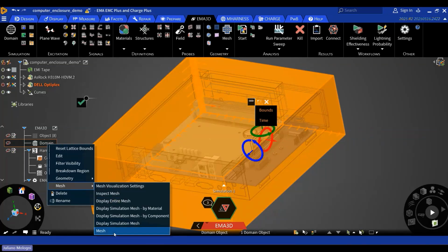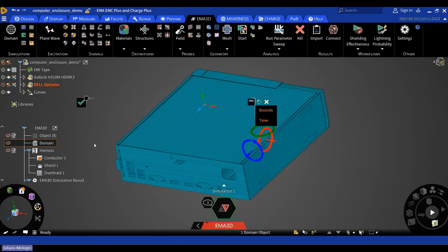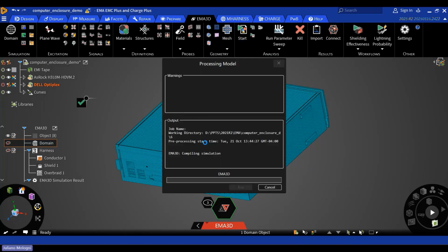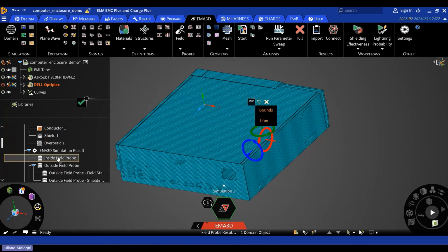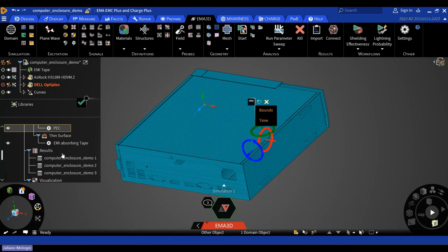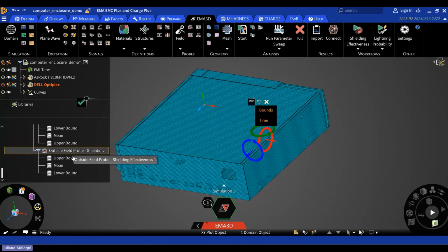You can get noise that is being induced in cables because of the fields from that PCB. So here's the grid for finite difference time domain, and you can just run the simulation. This simulation in here took 12 minutes on my laptop, so it doesn't take too long, right? And you can get fields, right? You can generate those animations. You can see radiated fields. They have a very neat way to compute statistical fields anywhere. So instead of having a probe, you can have a box and they can compute statistics on that.